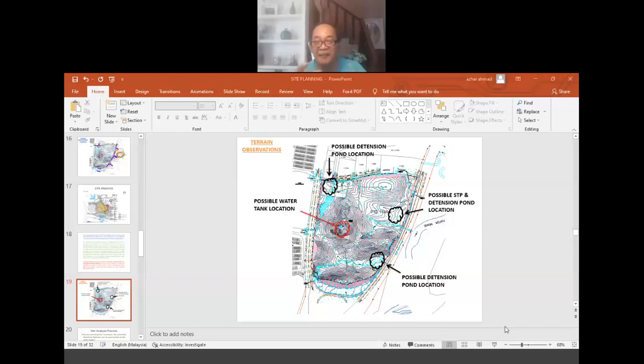So in UTM, the lake functions as a detention pond. So it stores water there. When there is heavy rain, water will be stored in the lake up to a certain level, and then it releases. So the release of water from the site is controlled by the level in the lake. We have what is termed a weir, W-E-I-R, weir. At the end of the lake, if you look carefully, there is a weir, a sort of dam with a certain height.